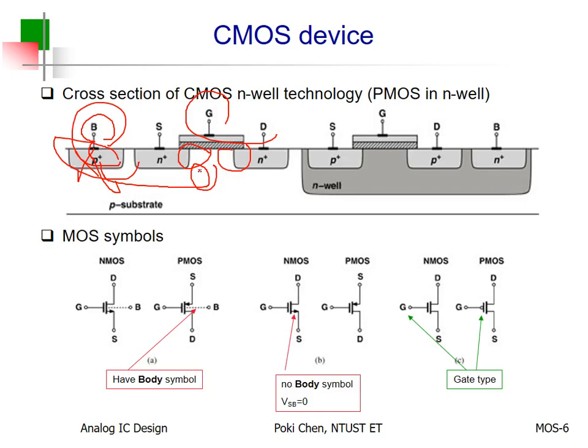And this is the reason why the doping for the body terminal is reversed relative to your source and drain. Again, in N-well, you have PMOS. The source and drain are doped with P plus. And how about your body? Again, no parasitic diode from the beginning, right? So you need to dope it as N plus for your body. Again, the body doping is totally different from the source and drain doping.